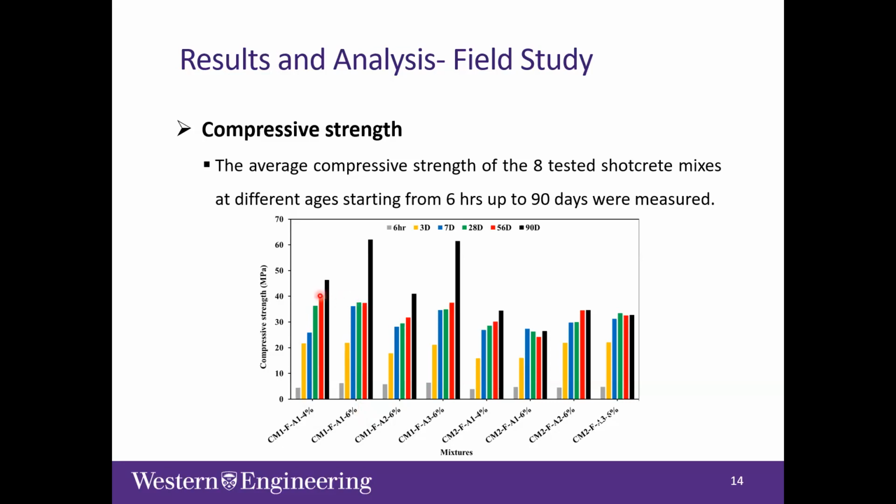However, we note a slight reduction in the compressive strength at 56 days, but still followed by a peak at 90 days. Similar behavior to this high ratio silicate accelerator at 6% is observed for the alkali-free accelerator, even with similar values. So from here, we can say that the new silicate accelerator has a competitive behavior to the alkali-free accelerator used in the market nowadays.